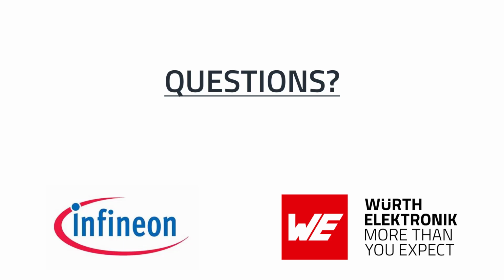First question here: how does the 2EP reduce the bill of materials? Yeah, I think I take that one. It's quite simple. If you remember one of the earliest slides I had where I was comparing our legacy product with the new ones, you already saw there that we quite reduced the bill of material because we integrated these integrated MOSFET switches for driving then the transformer. And this is basically the main takeaway, what you can reduce your BOM here, just to reduce the component count on the system.